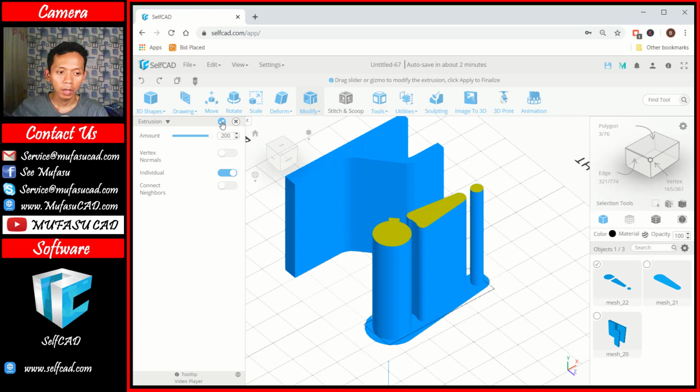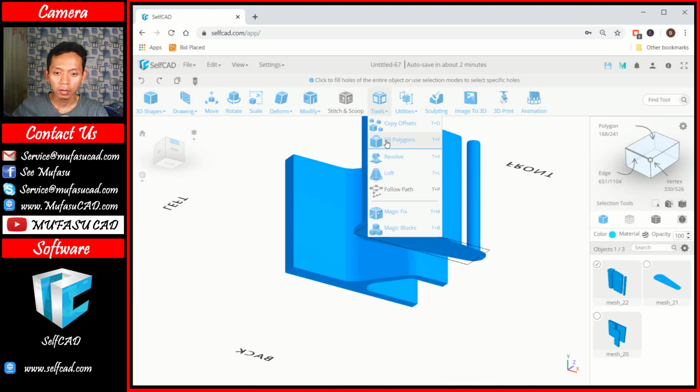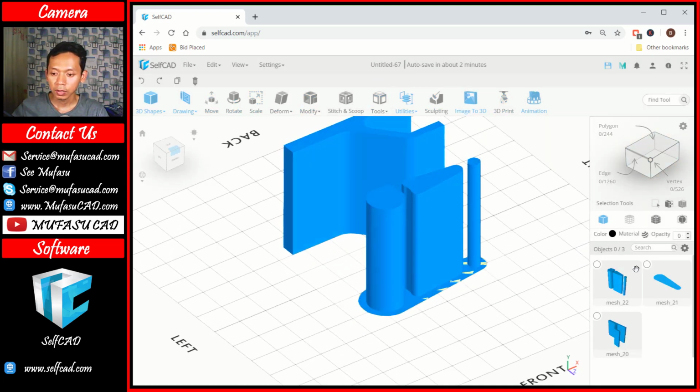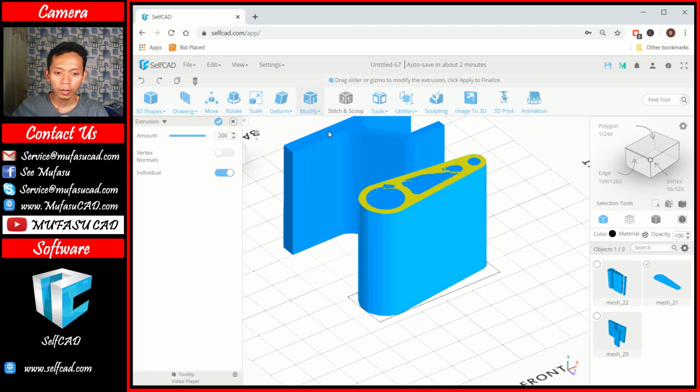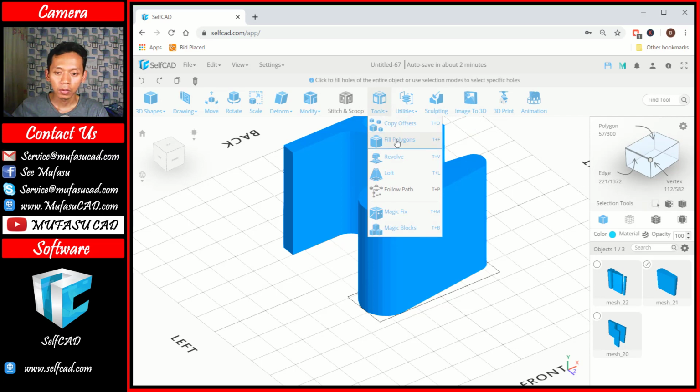You can click apply. You can uncheck these individuals and apply. Okay, we can use fill polygons again in here. The last, we can convert these objects into 3D models. You can use extrusion, and then uncheck individual, click apply, and in here we can use fill polygons in these 3D models.